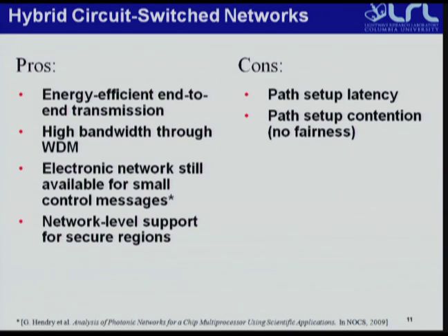And the cons you might imagine are, of course, the path setup latency. It takes time for the electronic message to go from one place to another along the chip, setting up the path. And this gets worse when we have higher loads, when more cores are trying to set up paths, and also if the paths are longer, they're probably more likely to block because they require more resources.